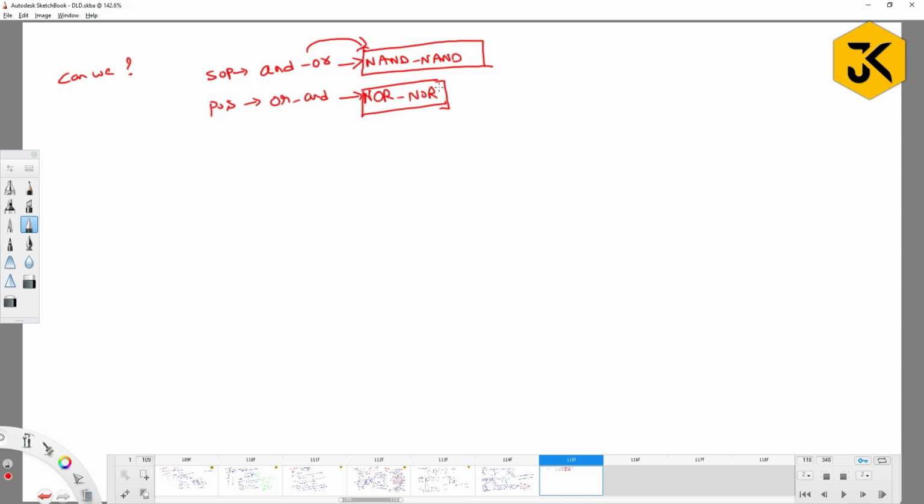But here the thing is, if you have a Boolean equation, can we implement it with the help of 2 by 1 MUX? Okay, fine. For example, if you would like to implement with an 8 by 1 MUX, I can implement it. But if I would like to implement with a 2 by 1 MUX, is it possible? That's the question, right? Or else, whatever equations are possible in NAND or AND OR, can we implement all of them using multiplexers? The answer is yes.